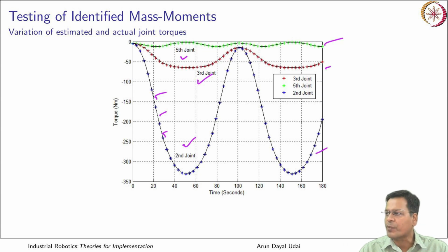So using this you can predict the load which is going to come, and mind you, the whole of this model was identified with all the supplementary loads in place. If a load is there, it is already fitted. I have acquired data for that and identified my mass moments with that. Because it is identified with all those loads, the torque I am going to get out of my model is exactly the torque which is going to come, not with the bare robot but with the loads which are there. So this will help me identify if there is any overload.